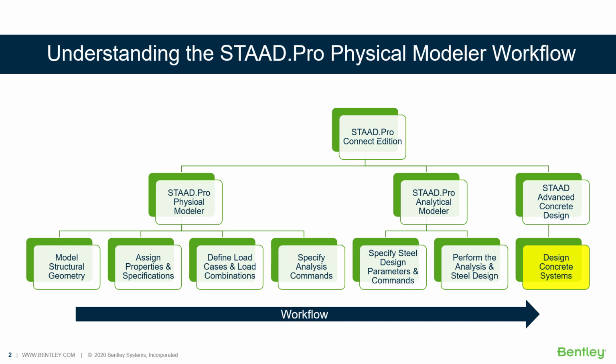The analytical workflow is used to model your structure using analytical elements. The analytical model is a finite element model of the structure, which is typically processed directly by the analysis and design engine. If you are an experienced STAAD Pro user, everything before STAAD Pro Connect Edition, this would be the workflow that you're probably used to.